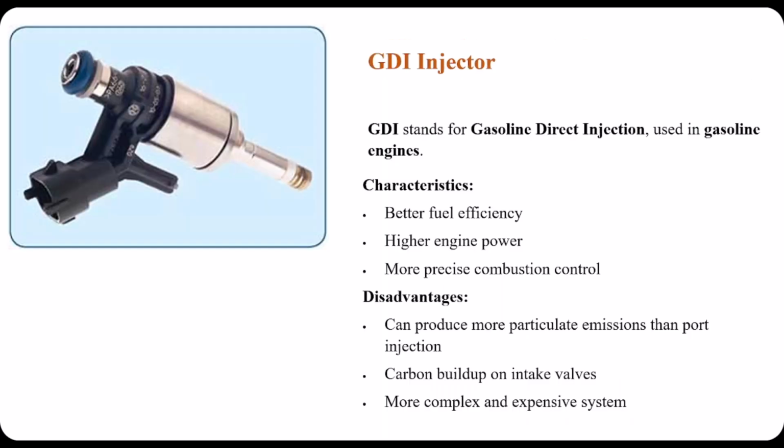Okay, but what about the GDI injector? The GDI injector, gasoline direct injection, which is used in gasoline engines with direct injection, consists of several main components. Its structure is similar to solenoid injectors, but it is designed to operate at much higher pressure.